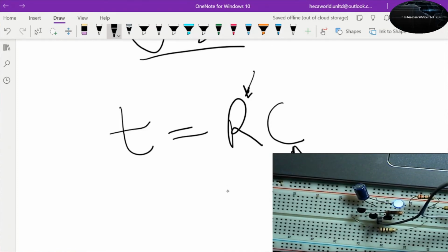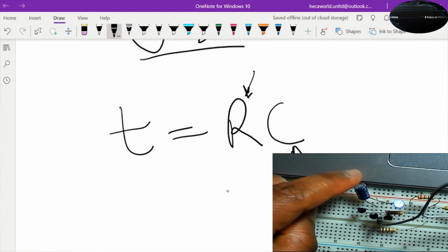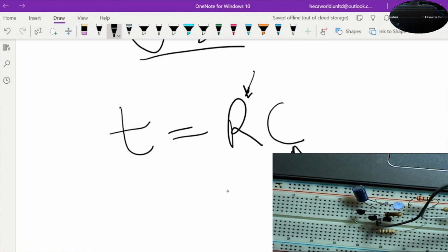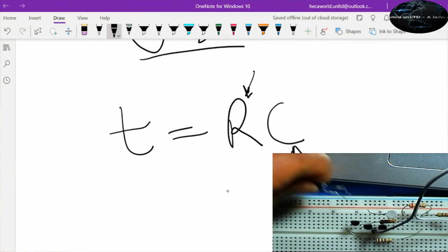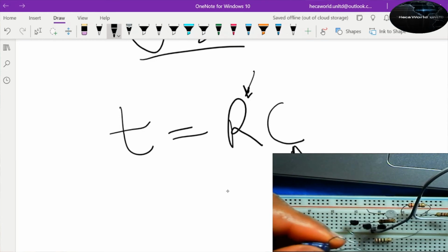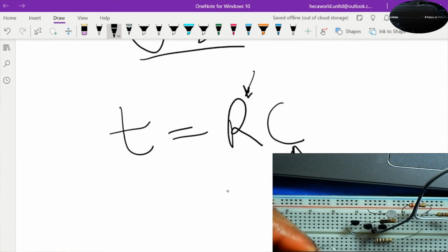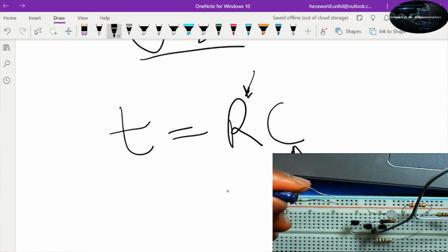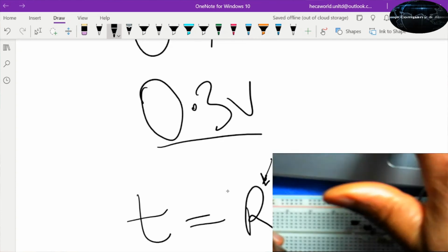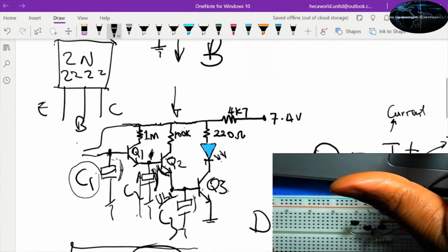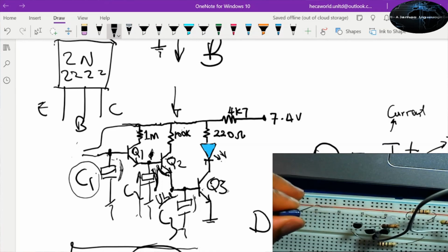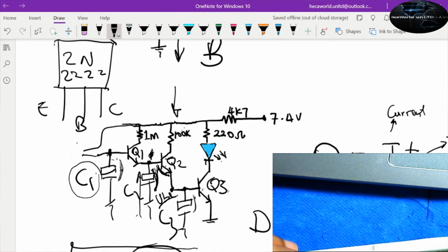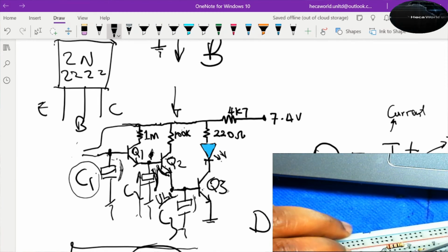All right. The last thing to do now is to take this capacitor and connect it to the first transistor, and it's going to be in the same way. So we're going to take the capacitor and discharge it. We will short it out with another wire or another capacitor. Just short the two terminals to make sure we discharged it, and then we connect it again from the base of T1 or Q1 to the ground. So from base to the ground.